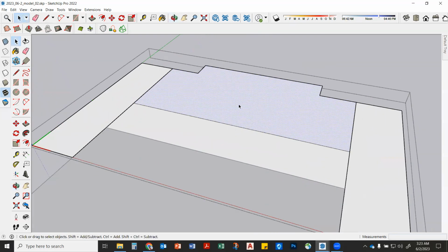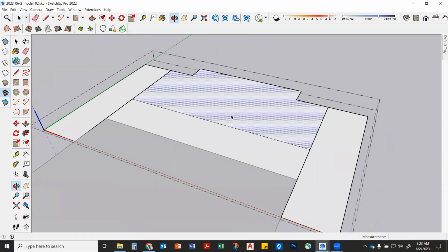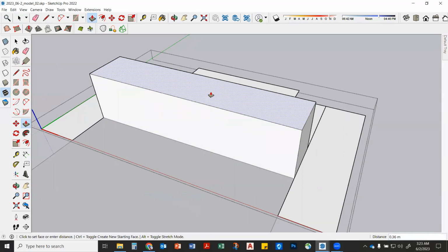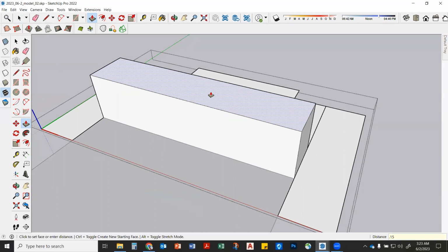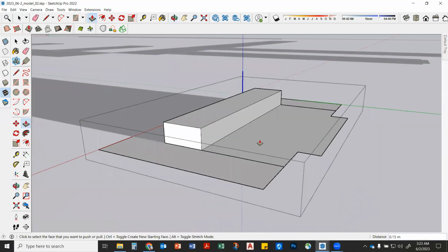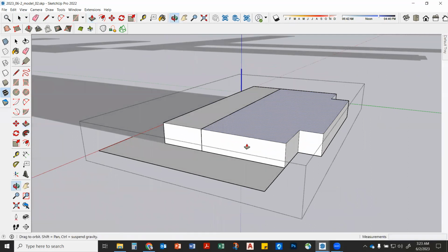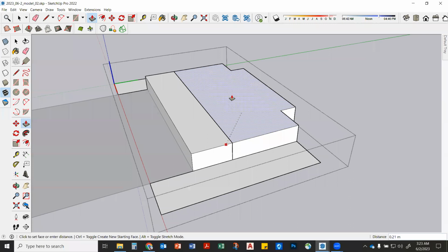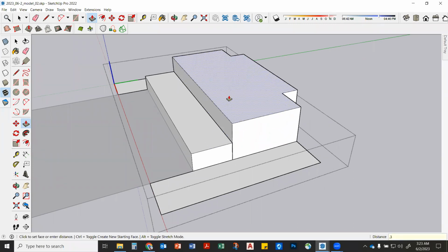So in here, I'm going to push this guy up. That's going to be 2 risers high, right? I could start on the bottom one if that makes more sense. Push here. That's 1 riser, 0.15, right? The only issue with starting with the bottom is watch, this will happen. I click here. Oh no, sometimes it actually limits it to this height, but this one will be 2 risers, right? So that'll be 1.5 would be right there, but we actually need it to be at 0.3, right?